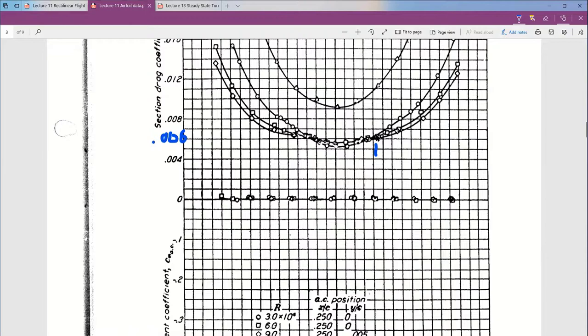So you're going to have to do this mentally every time you read off of here. I have to, or otherwise I'll get messed up. You have to essentially mark the lines in between and then know how much of an increment you've got going between this line and this line. So I read about 0.0062. Now if I'm looking at this chart and I write, I'm reading my drag as 0.00623971, what do you say? Yeah, you say I made up those last numbers, right? Because there's no way.